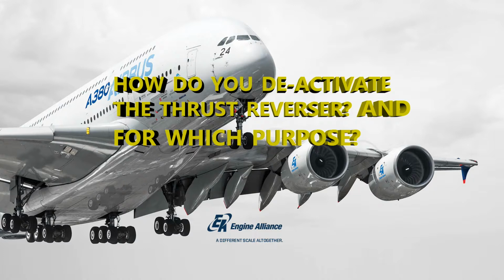Okay, and you're going to do that through the OMS, which is your onboard maintenance system. Be familiar with that. There's a lot of avionics involved, and if you're not familiar with these, do ask. Do make sure that you follow the step-by-step procedure when you're entering information or selecting choices on the OMS. This part of it is the power distribution monitoring and maintenance function. It commands the distribution center so that it stops the electrical power that's going to the actuator or actuation controller.